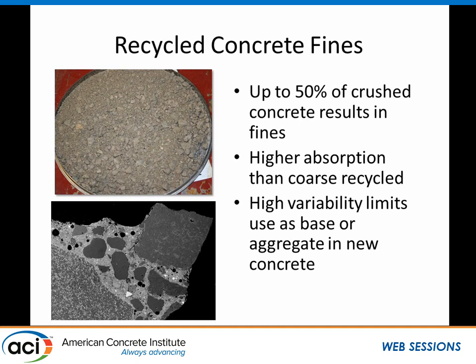I show a scanning electron micrograph in the lower image, and in that image you see the complexity of these particles. They include little grains of the original sand, chips of the original aggregate, and paste content. It's a very complex particle. So that high variability limits its use, and usually what people will do is use these things just as a fill, maybe as a base for